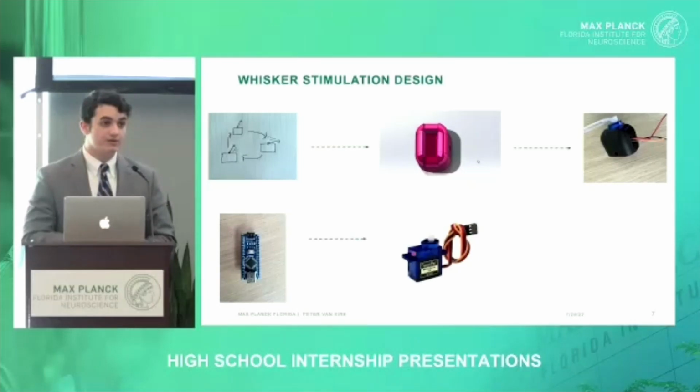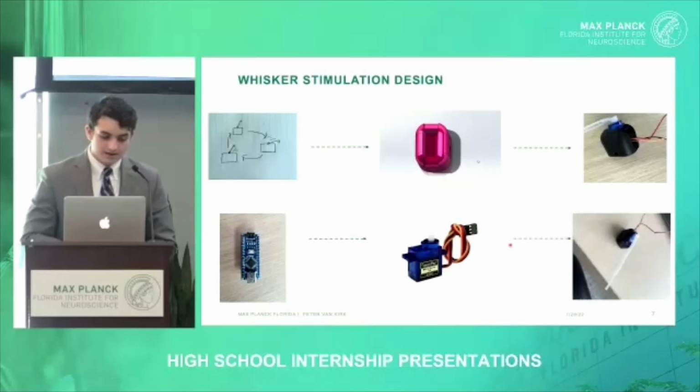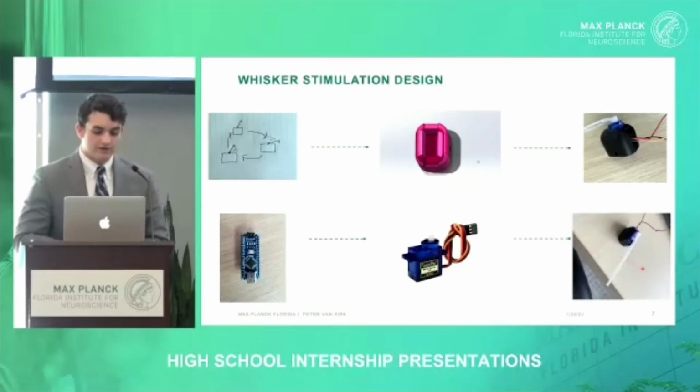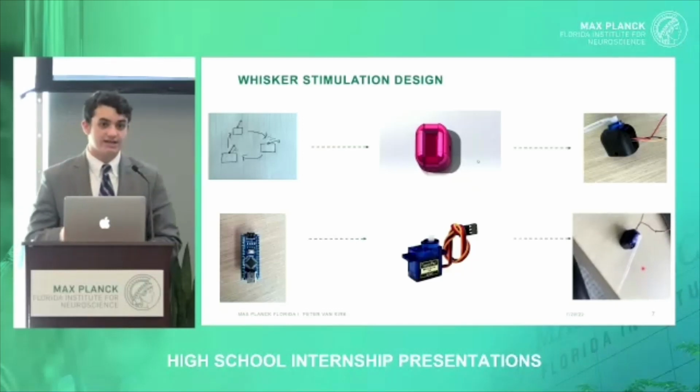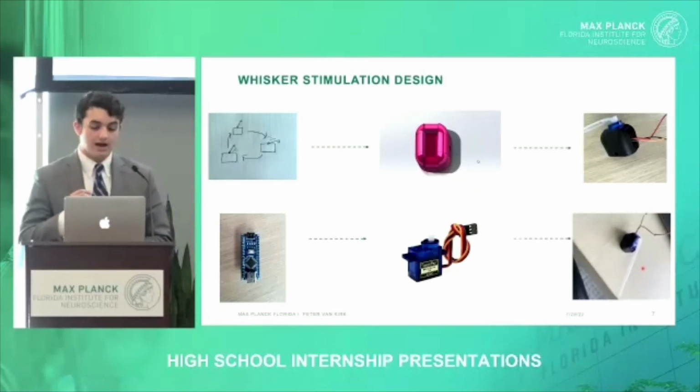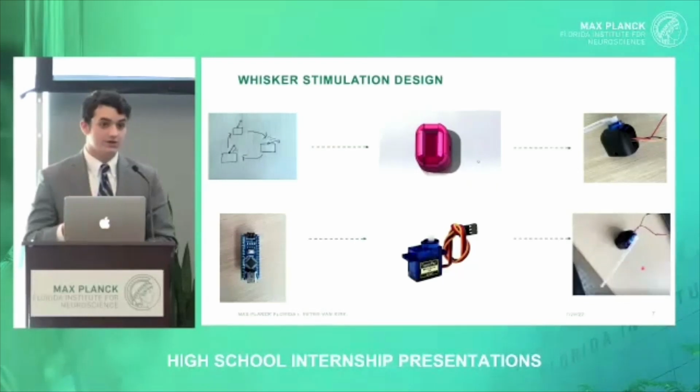The motor that I used for my project was a servo motor. This motor has a very low torque, which is the rotational force. So it's not pulling or pushing on these whiskers very difficult or very roughly. It is very light and it has a high frequency, which is exactly what we needed for these experiments. And lastly, here you can see a video of the motor actually working. And I did actually change the design to a pipette at the end because I found out that the musical wire that I was using as a hook was more difficult to get to stay on the whisker. It was easier just to have it in a pipette.